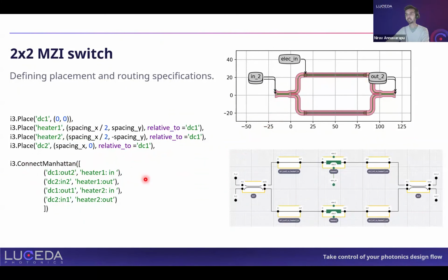And this MZI can be reconfigured with different offsets, heater lengths, etc., by just changing one line of code or just the variable which is passed to this. The final circuit can be exported back to Canvas to visualize the circuit schematic with every element involved, including the connecting waveguide, which is shown as a lumped element in this schematic.